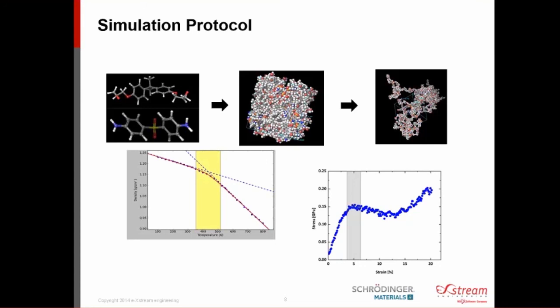You see a stress versus strain behavior, and we can pick out where the inflection point is. We can look at the first inflection point and relate that to the yield. So we can see an elastic behavior of the polymer in the initial straining. If you look to the left of the plot, starting at zero strain, you see this kind of a straight line. That's the elastic behavior, and it goes up and it begins to yield.